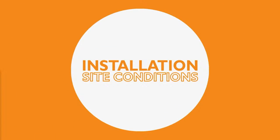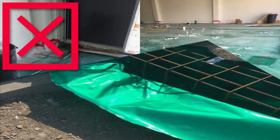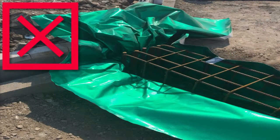The general conditions around a site are often as important as specific details when it comes to validation of membrane installations. In these images, you can see that patches have been applied to the membrane haphazardly and messily. The marker spray is still visible around patches, indicating that the applied patches are too small to give the required overlap.